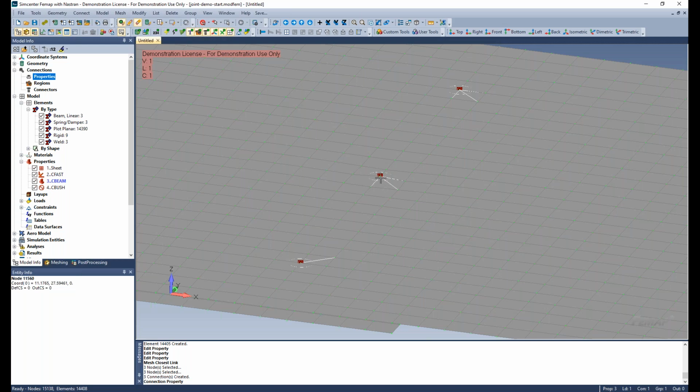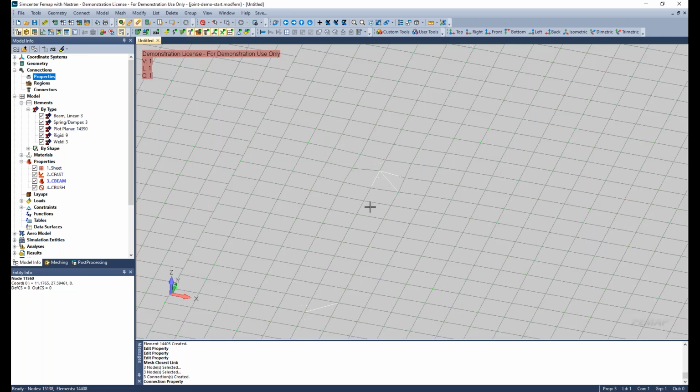And what Nastran would have done is it would have taken this node location, or the node I used to define the location, and projected it onto each patch. Then, based on the diameter of the fastener, it would have picked which elements to connect automatically. Given the mesh size I chose, and the fact that my fastener is on par with being the size of an element, it probably would have grabbed all 4 of these and connected them together. And that's the beauty of it: it would have done that more or less automatically for me.